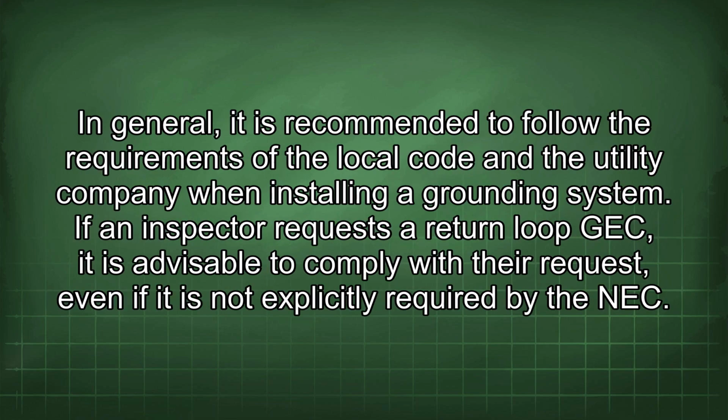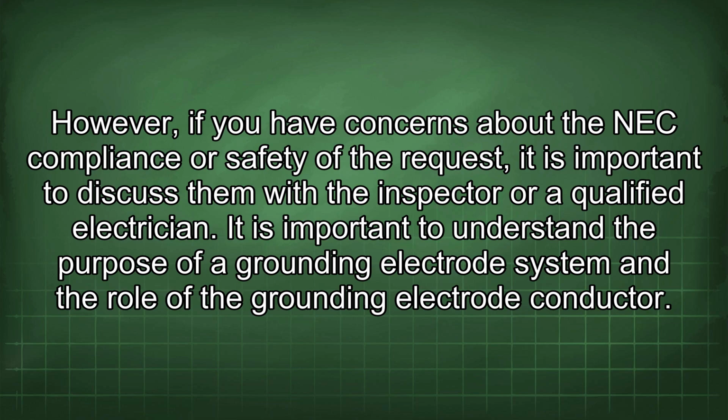In general, it is recommended to follow the requirements of the local code and the utility company when installing a grounding system. If an inspector requests a return loop GEC, it is advisable to comply with their request, even if it is not explicitly required by the NEC. However, if you have concerns about the NEC compliance or safety of the request, it is important to discuss them with the inspector or a qualified electrician.